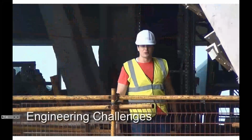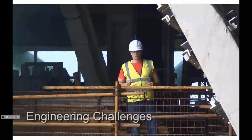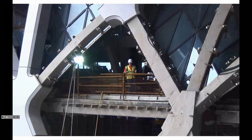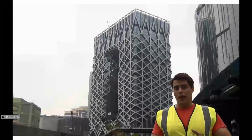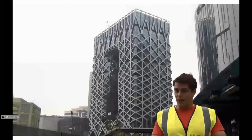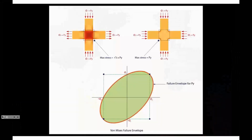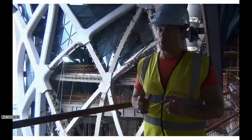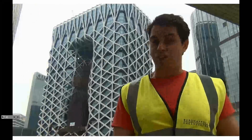So why was the exoskeleton connection design such a big deal for engineers? It's because all of these members right here are coming together at very complex junctions that no codified approach covers. So right away, codified approaches are out the window. The second thing is we had hundreds of load cases and members that were designed to their plastic capacity and were subjecting the connection to 6 degrees worth of forces and moments. This meant that all the plates in the connection would be subjected to a complex stress state. That can only easily be analyzed via finite element analysis, which of course to me was awesome because I've always been interested in finite element analysis.